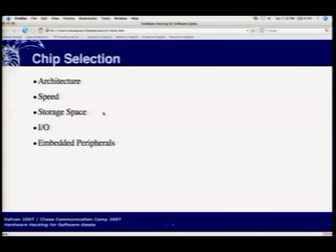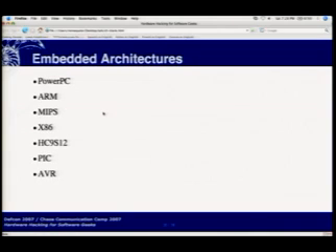As well as communications, there's sometimes stuff just completely built into the chip. Real-time clocks and watchdog timers are pretty common, which are useful for setting the chip to do something in the future. Basically, if you have a part of the code that you want run every n seconds, or resetting the chip if something goes horribly awry.